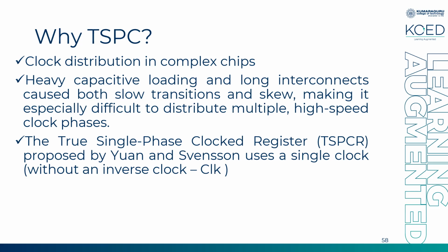Now if there are 4 stages, the clock has to be given to each stage. For all the stages, the clock will not go at the same time. That is clock skew. And the stages will not act in the same way because the clock is not distributed at the same time. For example, first stage 0 nanoseconds, second stage 4 nanoseconds, third stage 8 nanoseconds. It may differ. This difference, there are thousands of reasons for it, but this difference will cause degradation in the working of the circuit.